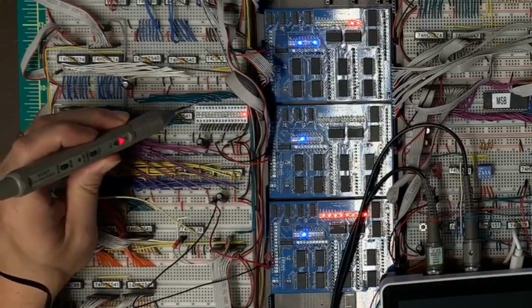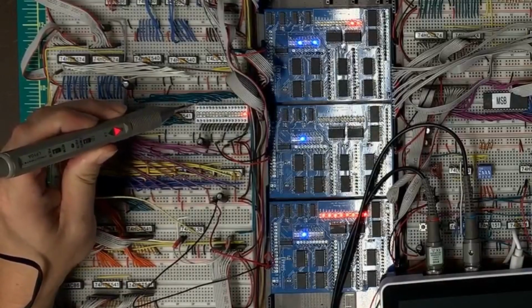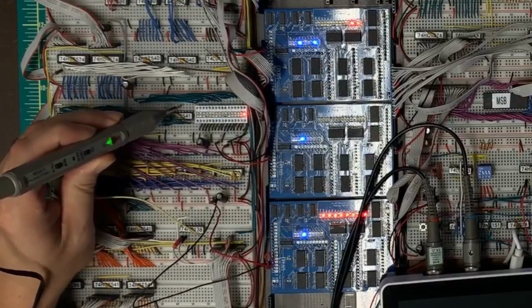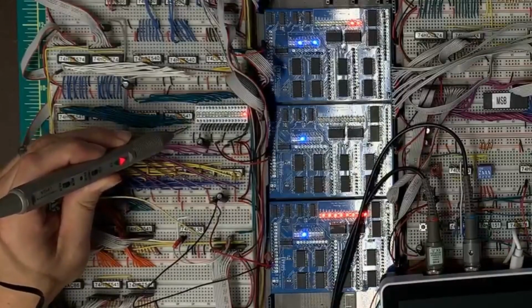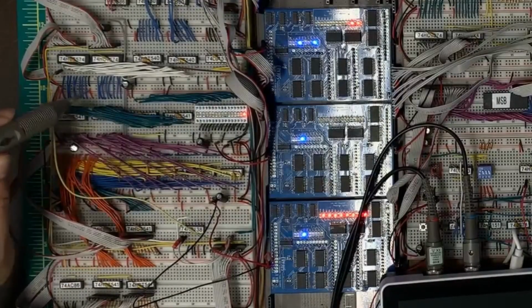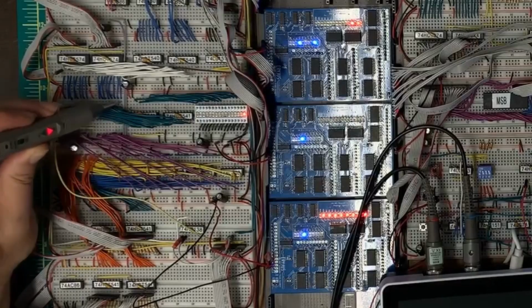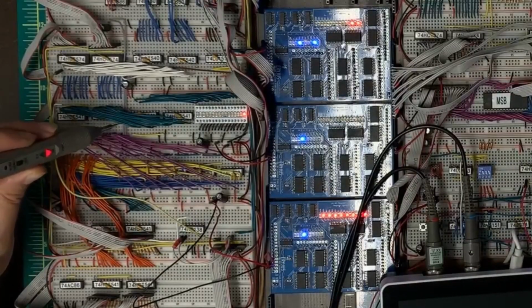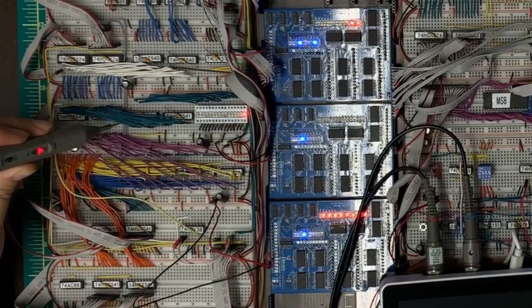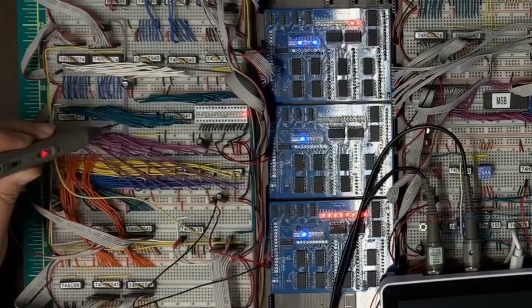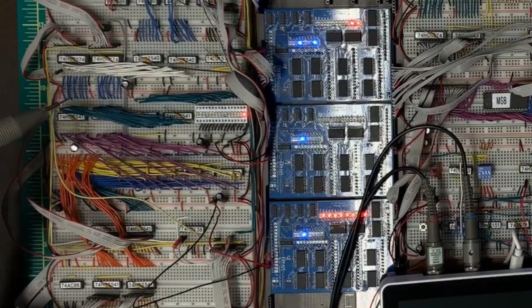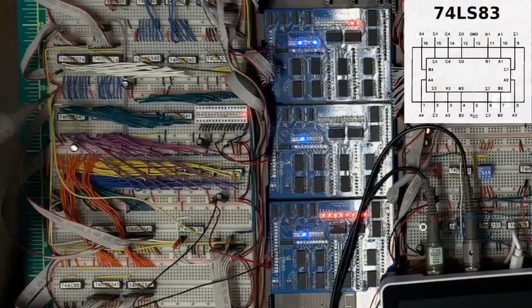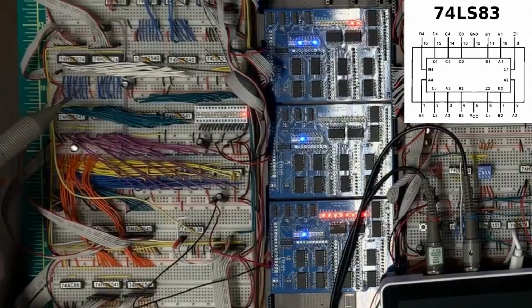On the line driver that is driving that signal, it is outputting high, which means that I get high coming in. Tracing that backwards, that means I've got a 1 on the ALU bus, internal bus, which means that I'm adding to have a value of 1 for the least significant bit. Now I've got to pull up the pin diagram for the full adder here, and I'll stick a copy of this up on the screen for you as well.